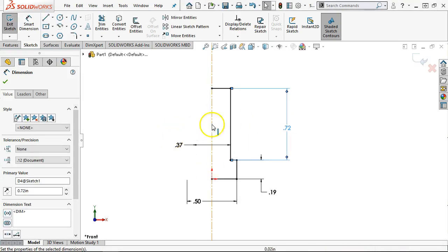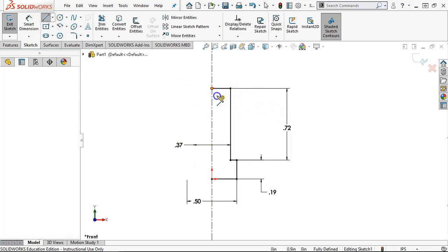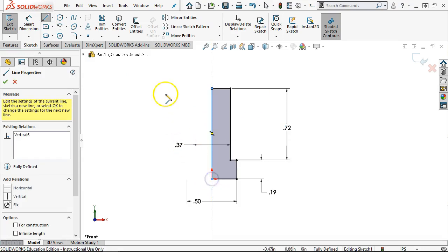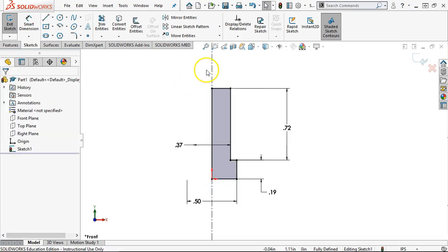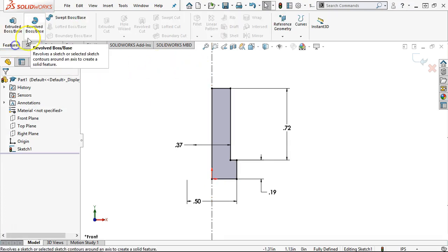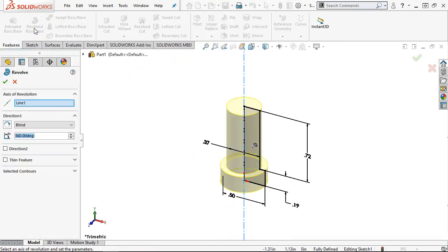All right, so at this point, with revolves, it's going to see this open edge and say, do you want to close your sketch? And I'm going to say, sure. Or I can come over and grab another line, and we'll drag from point to point to create that region. Since there is only one center line, that will become the basis of the revolve, the axis of revolution. So center line becomes the axis of revolution. All of the enclosed region gets revolved.